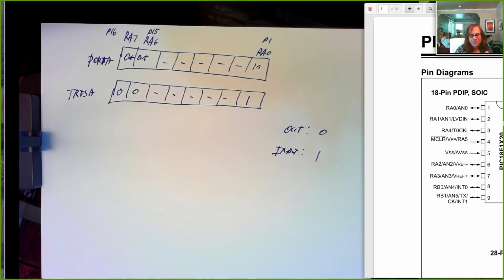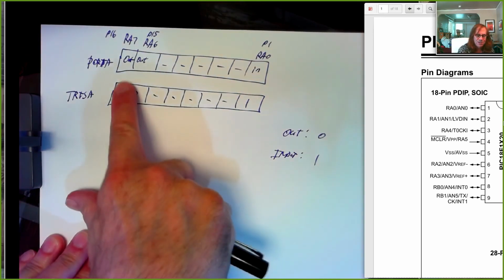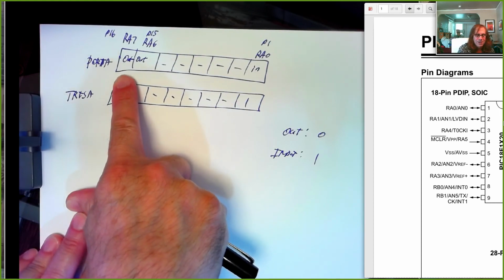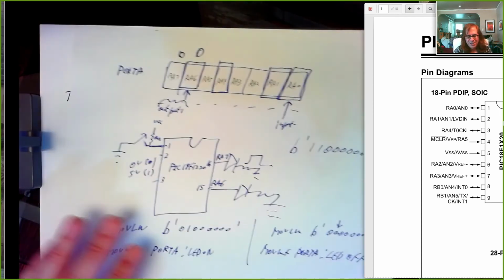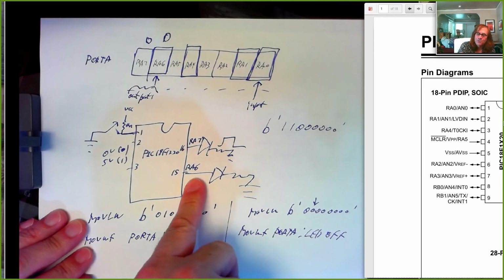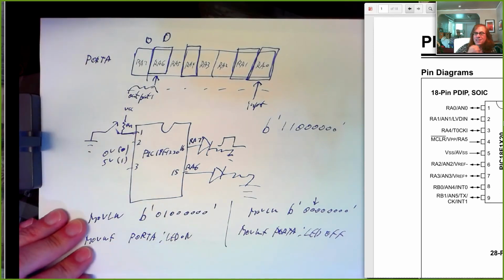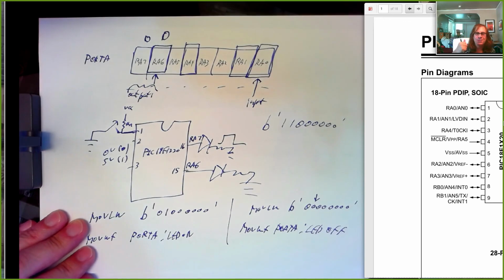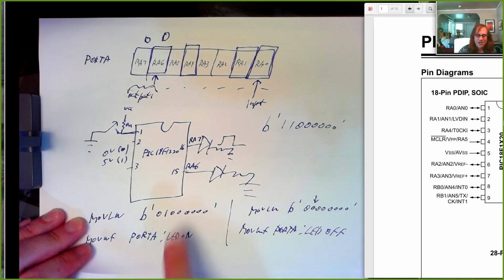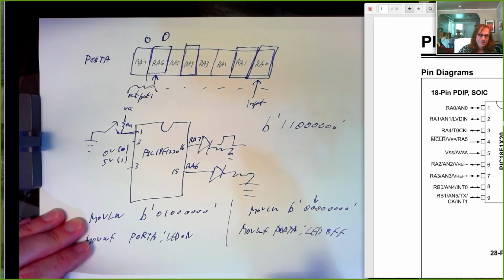So if you want to read a voltage level from this pin, you need to stop driving a voltage level to that pin. Or let's go the other direction. If I want to drive an LED, I've got to have circuitry inside here which says, hey, make this high or make this low. But if I want to read a voltage level that's coming in from a switch, I need to disconnect that internal circuitry. So I'm not driving it to a 1, I'm not pulling it down to a 0. I want to totally disconnect it. And that's something in digital logic we call tri-stating the output. So it's just a fancy way of saying we disconnect the output drivers from this pin and we say, hey, send a voltage in and I'll read the voltage level you're supplying.